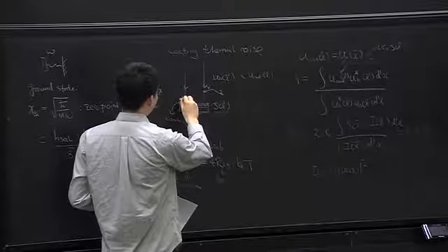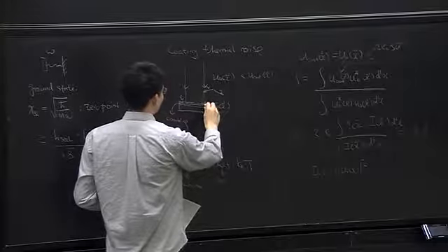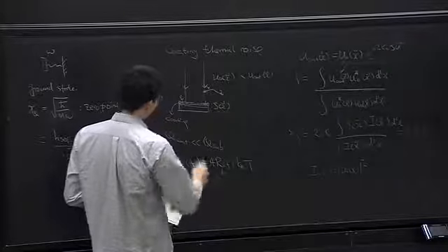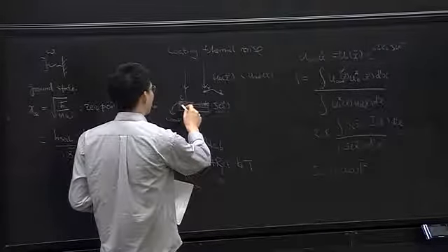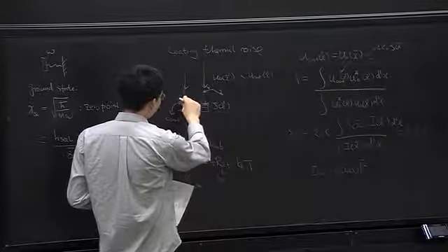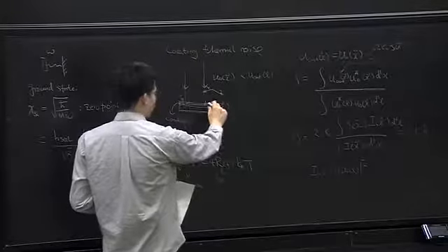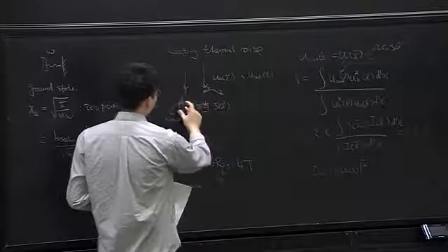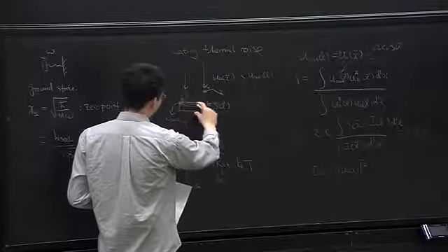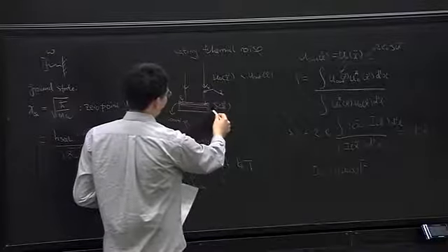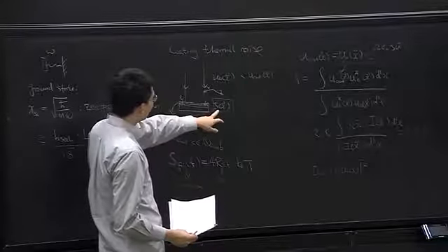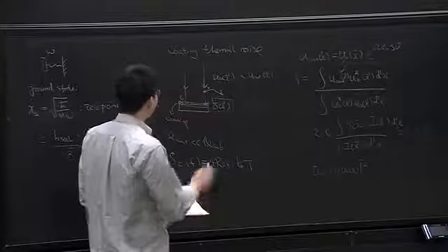So the F here in the coating, which is up and down, or it could even have force in the transverse directions, is much bigger than any fluctuating force in the substrate. And because the coating is attached to the substrate, this force will try to bend the substrate, and this bending is basically the dominant piece of this vertical displacement of the front surface.